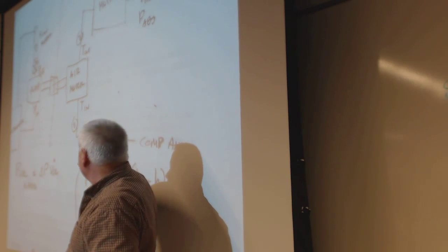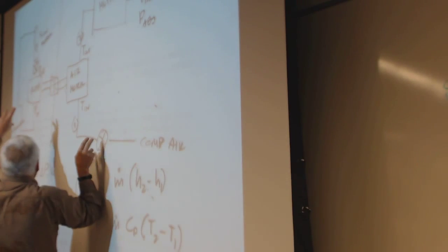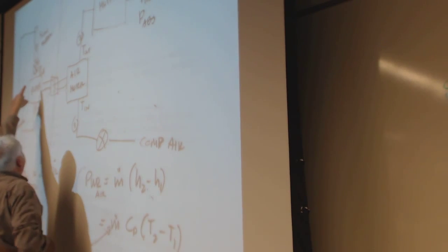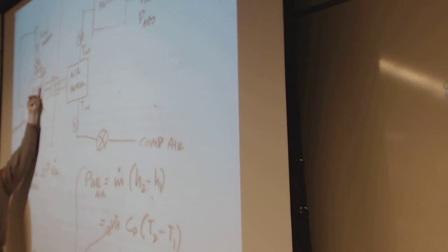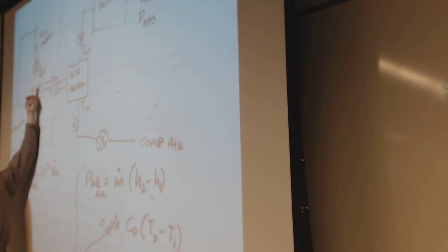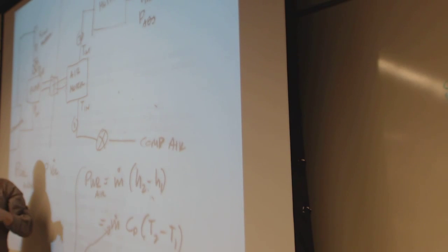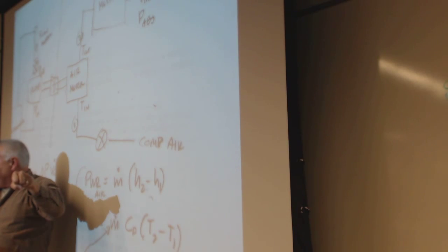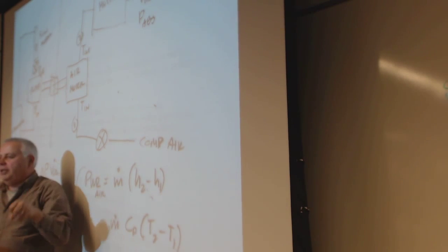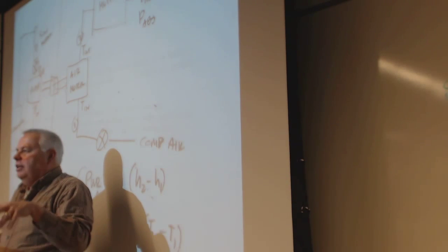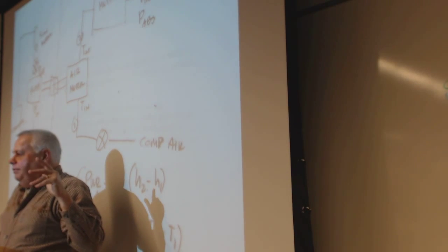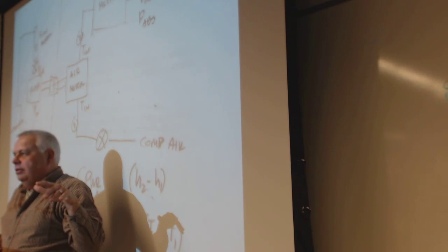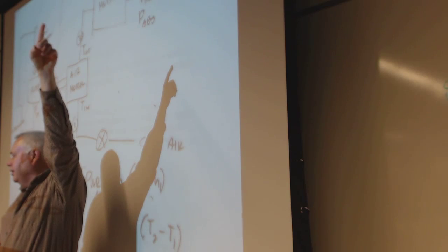Basically, probably the best bet is to have somebody operating the load valve here, because basically what happens with the pump, it's creating a volume going forward, and the system pressure it sees is, as you close a valve, it's generating a back pressure. It's generating a resistance, which causes a back pressure. If it causes 15 psi of back pressure, that would be equivalent to as if it was pumping something up 30 feet, however high. We're creating an artificial load.